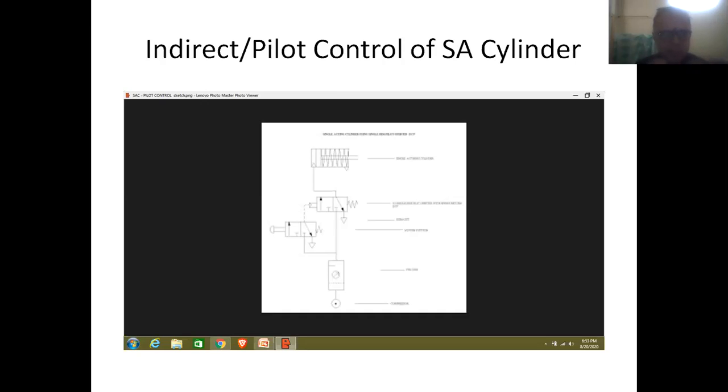The inlet of the valve is fitted to the pipeline coming from the compressor, and the outlet of the pilot valve is fitted to the left hand side of the DC valve. Finally, the exhaust of the pilot valve is fitted to the pipeline that is entering the atmosphere.